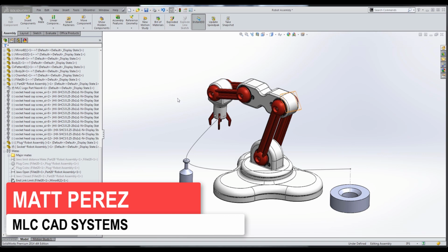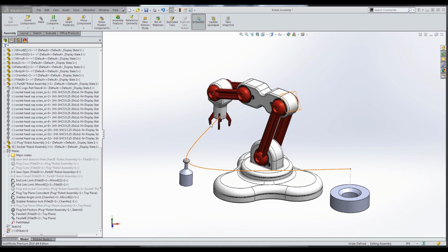In the last video we talked a little bit about what we're doing here and we created this 3D sketch that will define the distance and path that our machine is actually going. So that's the hardest step right there. Now a lot of what we need to do just comes down to details. One thing that I want to change is I want to go back into the pathmate and show you some of the options you have.